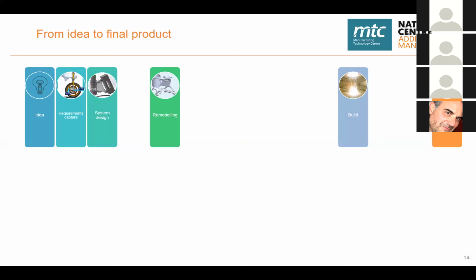So in the case of the fork end, the connections with the brake caliper, for example, are areas that we are going to keep anyway. It doesn't matter what our geometry is, we will be using the same connection. So we need to keep them without knowing what is going to happen in there. But then we can add loads. And then from there, what we can do is create our concept.